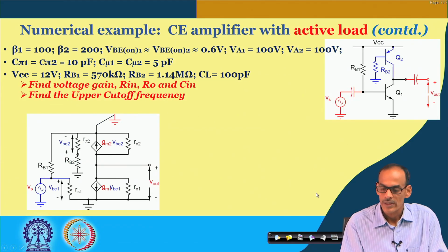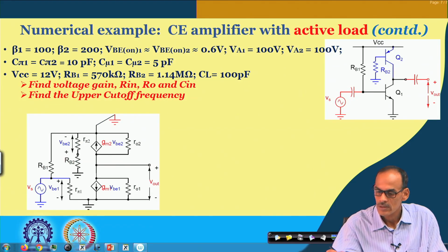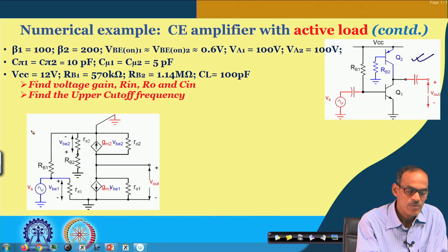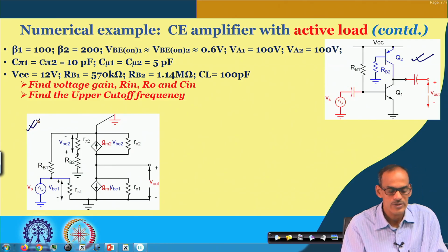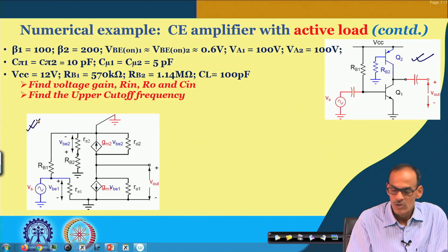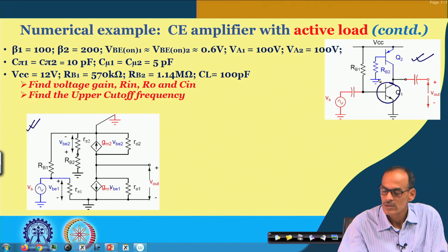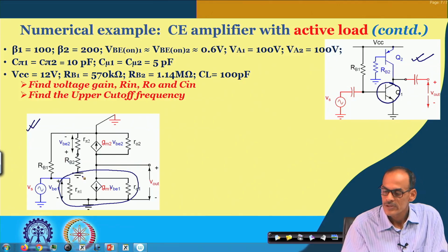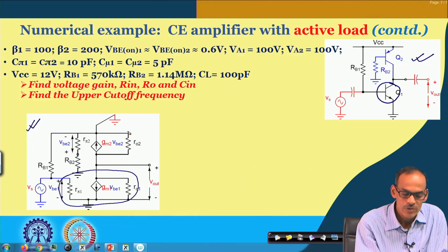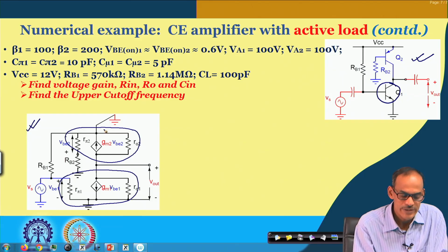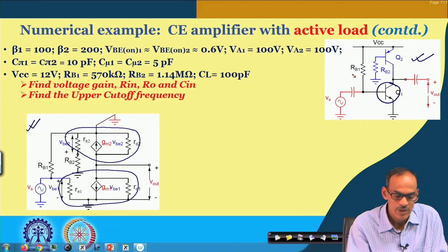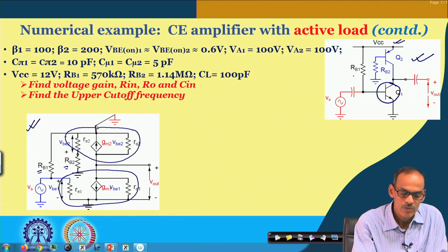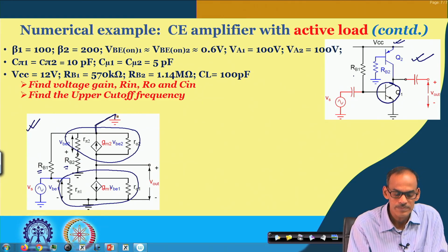So, here we have the circuit, shown for our reference, and the corresponding small signal equivalent circuit is drawn at this place. For transistor 1, Q1, we have the small signal model drawn here. Likewise for transistor 2 we have the small signal model drawn here, and then we have RB1 here, RB2 here, and this node is AC ground, so that is why it is connected to ground.